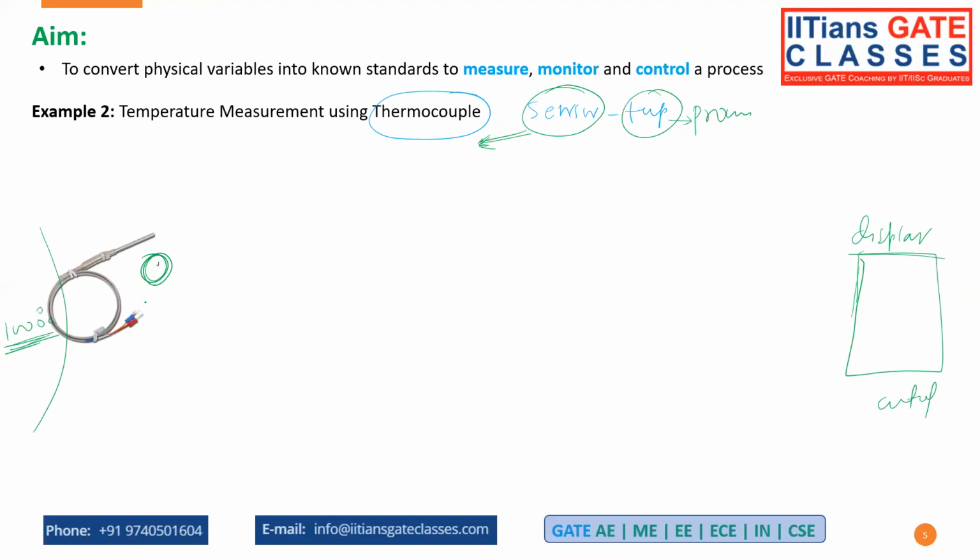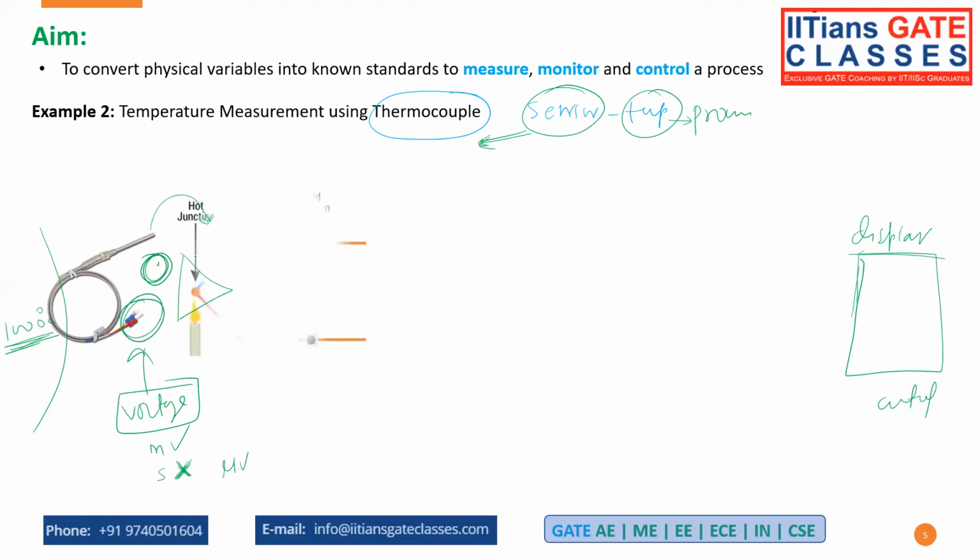So what this will provide, the output will be voltage. See, again it provided the output as voltage. So is it a meaningful quantity? Yes, but its strength is not good. If you measure with the thermocouple, the output is going to be in microvolts or very few millivolts, because its sensitivity is going to be very less, right? So in that case, you have to go with the signal conditioning circuit, and you can put your op-amp here. I have not put any op-amp, so you can put your op-amp here.